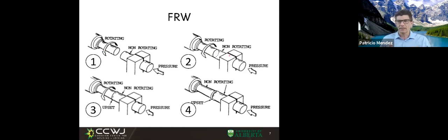And that heat is not meant to melt, like everything we have talked about so far. Always below the solidus, and often below the minimum eutectic of the material system, because sometimes you might have some low melting points that you didn't mean to have. And this localized heating creates localized softening.